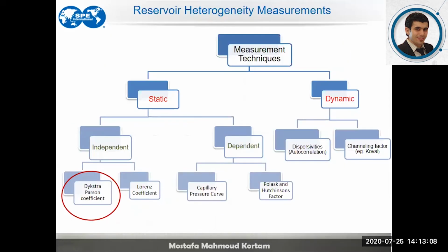So even the layering was also defined by reviewing the production data and the progress of the water oil ratio, by either a chain plot or the normal plot of log water oil ratio. There is some assessment on how to quantify the heterogeneous system. Now we understood that we have a layering effect and a vertical sweep deficiency, and inefficient flooding is being propagated on the vertical scale, but how to measure, calibrate and quantify these parameters?